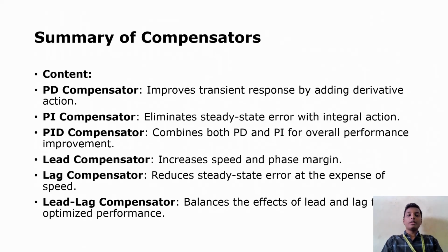Summary of compensators. PD compensator: improves transient response by adding derivative action. PI compensator: eliminates steady state error with integral action. PID compensator: combines both PD and PI for overall performance improvement.